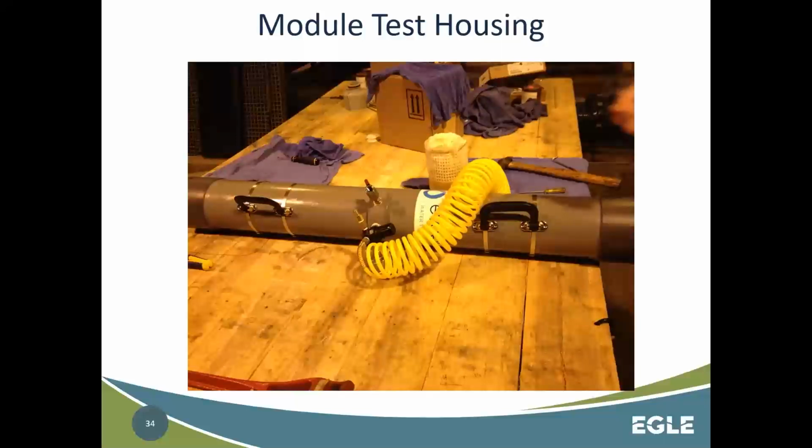I guess you call it a test housing. So you would actually take one of those modules, valve it off, and remove it from the rack, bring it out to your test bench here, and stick it in this vessel, and then you put an air compressor to it, and you look at that potted end, and if you see air bubbles coming out, then